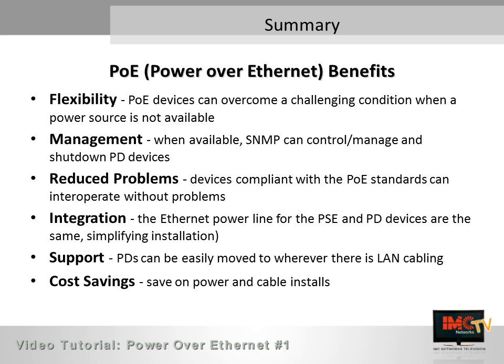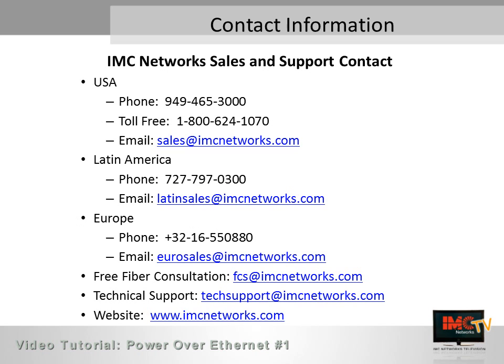Integration is also simple because you're using the Cat5 Ethernet power line for both the PSE and the PD devices. Support is very useful because the PD devices can be moved easily to wherever there is LAN cabling. And finally, there's a cost savings. You're saving on power and cable installations.